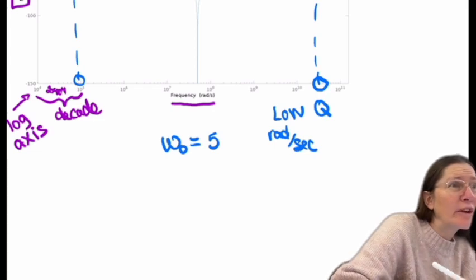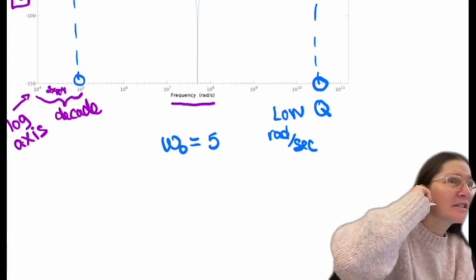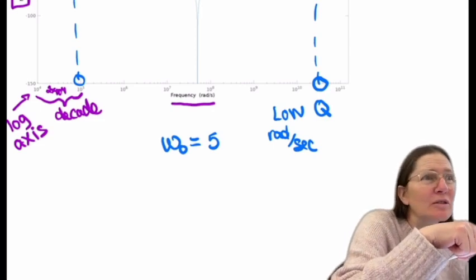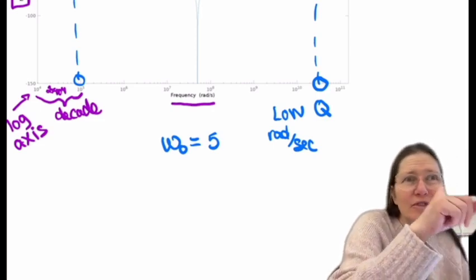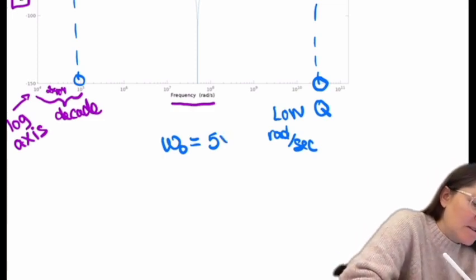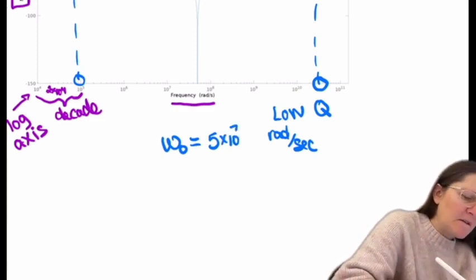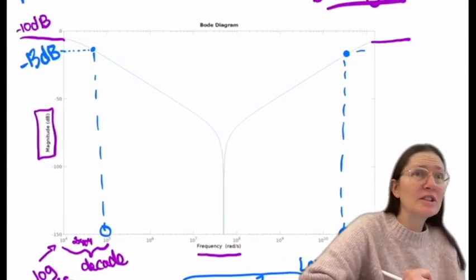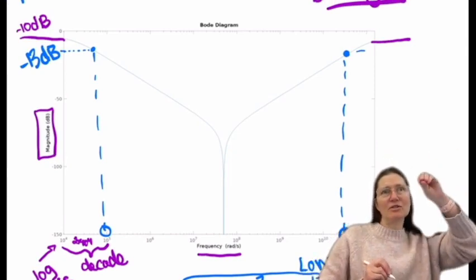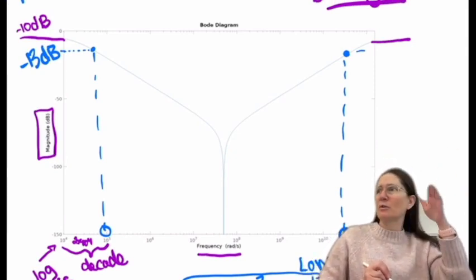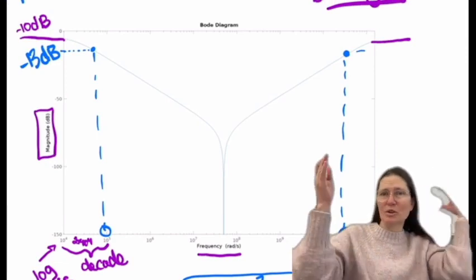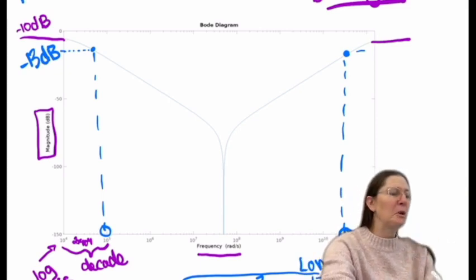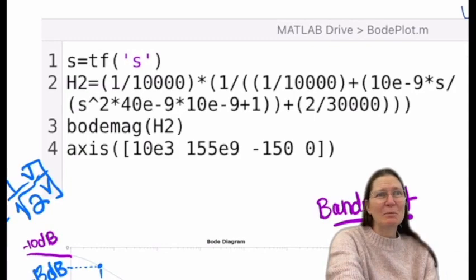Okay. So on that, can you click where that omega naught is, and does it tell you the value? Because on MATLAB, it will tell you the actual location value. Like if you click on that point, it will say its frequency equals. Okay, so in MATLAB, you can hover over it until you get down to minus 13 dB, and then you can see the frequency there. So that would be where you could determine where your corner frequencies were, which is a nice feature of MATLAB, but you do have to know the specific syntax of it to be able to plot those.